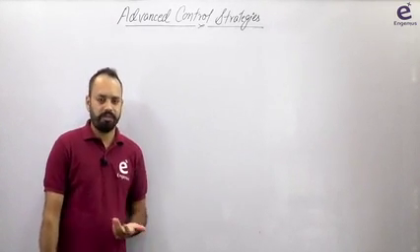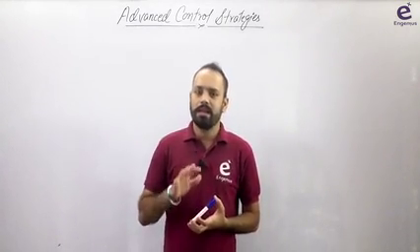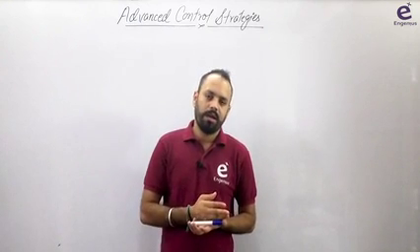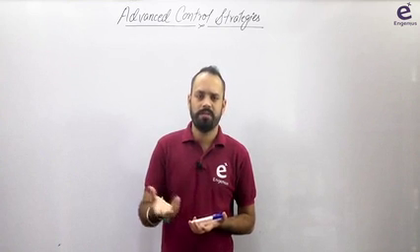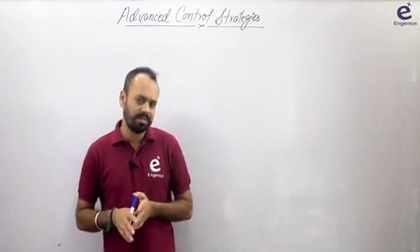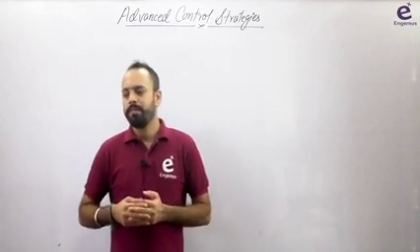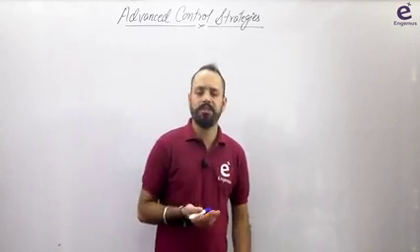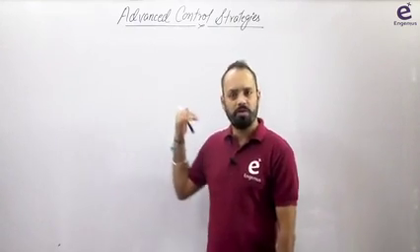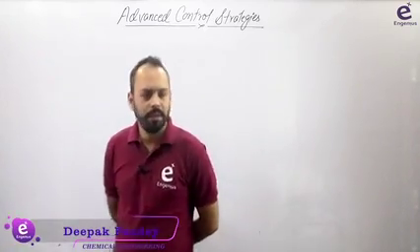We also discussed that valves are direct acting or reverse acting. So I told you that an air to close valve is always taken as direct acting. There can be a situation when even an air to close valve can be taken as reverse acting, depending upon various other things associated with the valve. But for our discussion, it is sufficient to consider that an air to close valve will be considered a direct acting valve and air to open as reverse acting. If you know the nature of the valve, you can always check the nature of the controller by checking what is happening to the measured variable and then what is happening to the controller output. If the nature is the same, then the controller is a direct acting controller. ऐसे ही था, है ना?